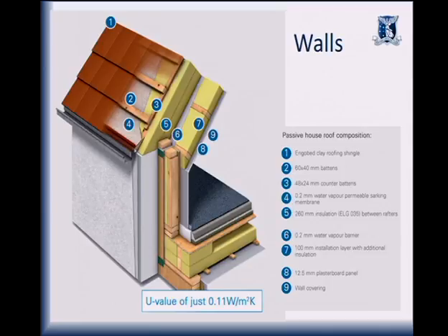So concrete seems to keep coming up. It's very thick, it's very heavy, it must have a good R value. It's fairly poor overall. They're one of those slides, and you can look at those slides and get an understanding of this stuff later. One of those slides shows that 150 mil of concrete, which is what, that thick, has the same R value of 20 mil of plaster or 6 millimetres of polystyrene. So concrete's actually pretty poor. Thermal mass, very different story.